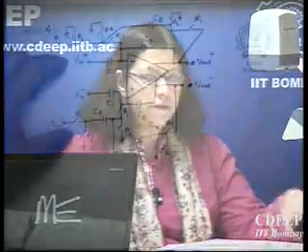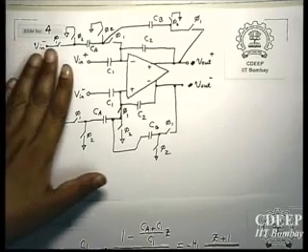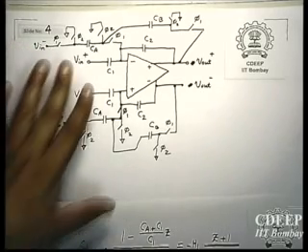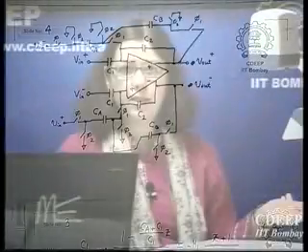However, now what about noise? If you use the same value of capacitors, then your kT/C noise will be double here, because you have twice the number of capacitors compared to the single-ended version, right? And therefore, your signal to noise ratio now will be double compared to the single-ended case if you keep the value of capacitors unchanged.